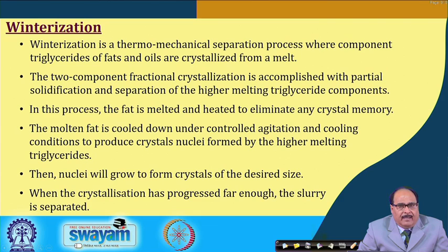Then the next process is the winterization. In fact, winterization is a thermomechanical separation process where component triglycerides of fats and oils are crystallized from a melt. The two component fractional crystallization is accomplished with partial solidification and separation of the higher melting triglyceride components.